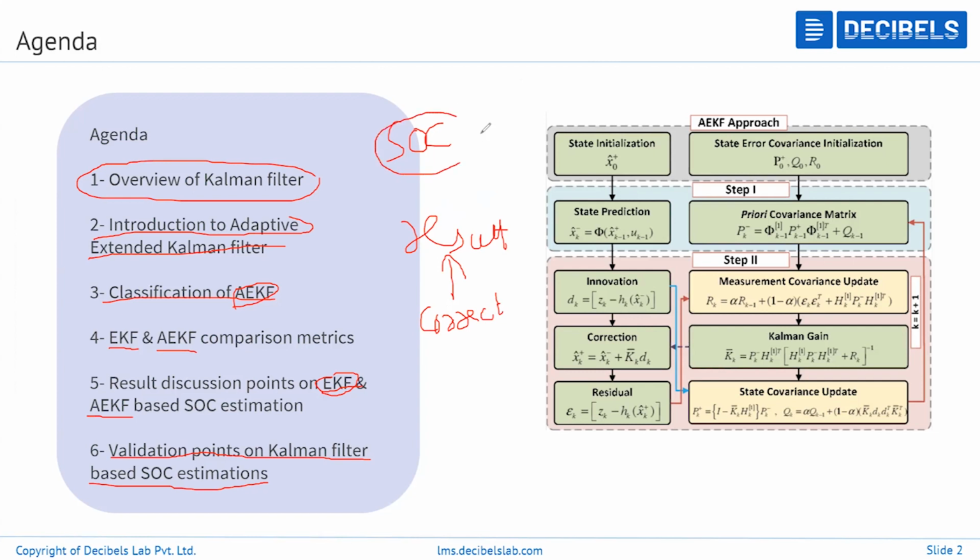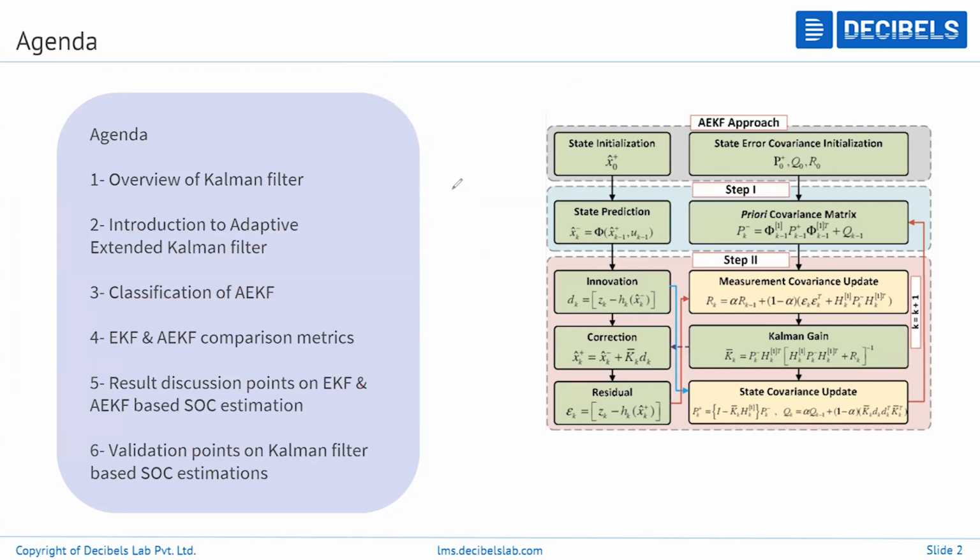When you talk about SOC, there are other parameters such as SOH and SOE. On what basis can we say these are correct? Because these parameters, SOC, SOH or any other cell parameters, are not direct measurements. They are indirect; we call them estimations.